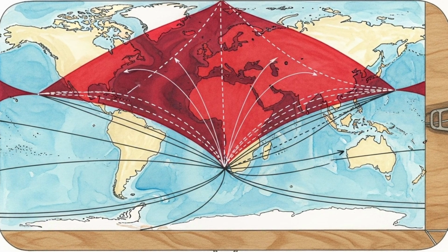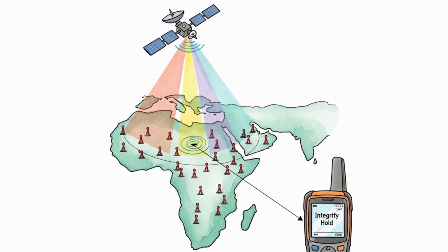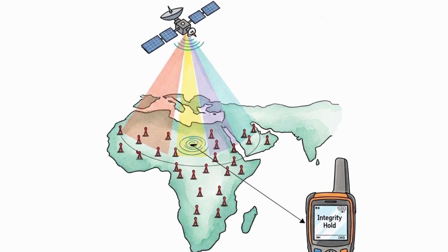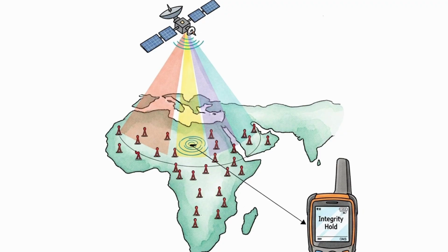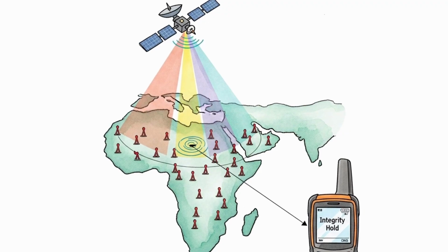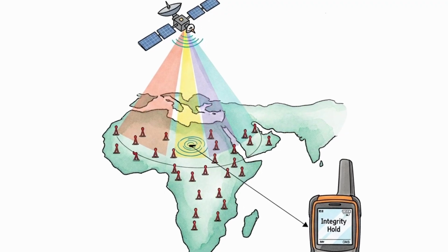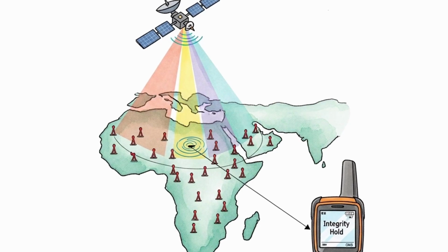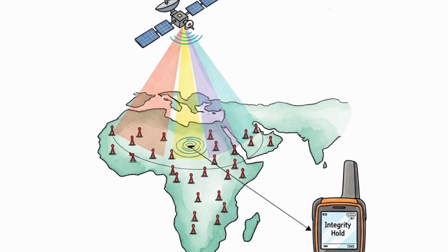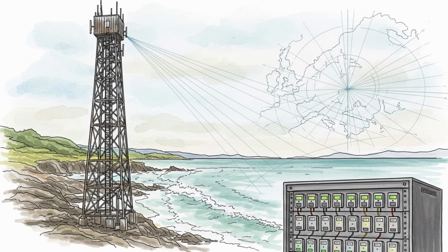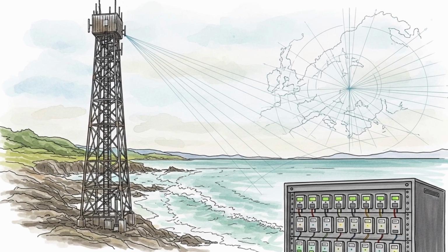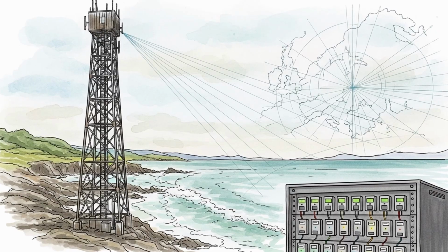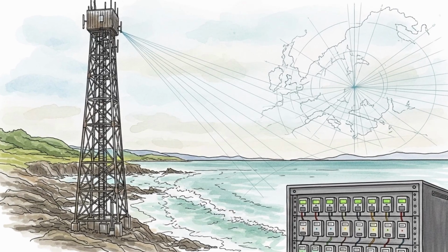Black start and restoration procedures assume that some areas may separate or de-energize. The sequence is well defined. Assess equipment condition. Build a cranking path from black start sources to target stations. Energize sections step by step while watching voltage and reactive power. Pick up essential loads in stages. Synchronize islands when frequency and voltage are stable.